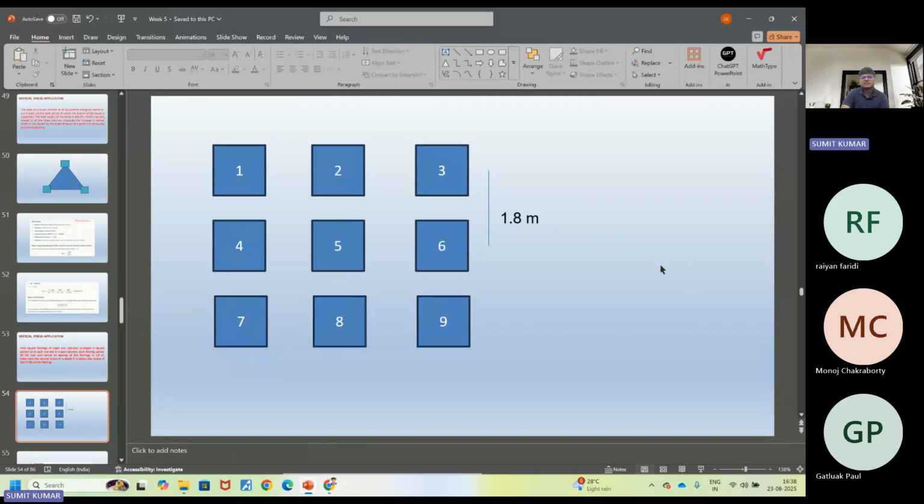Okay, let me explain the thing orally, then we move to the solution and you will get a better understanding of the things. So let our target footing below which we are going to calculate the stress be maybe 3. So the R value for that is going to be root under 3.6 square plus 3.6 square. You understood why?